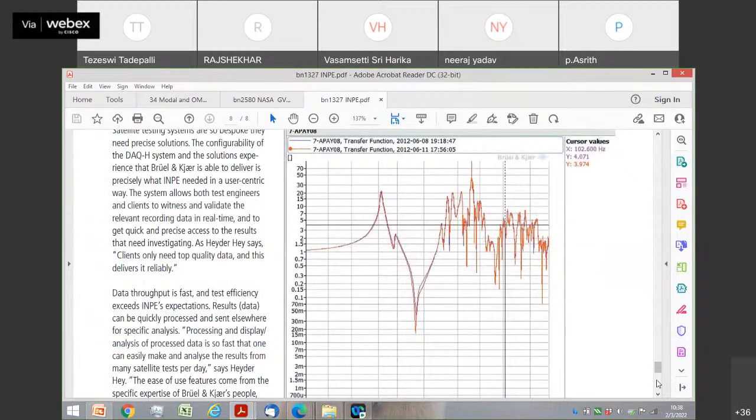Any questions, sir? Hello, sir. I'm Neeraj. Yes, yes, yes. Do you have progressive wave tube facility for the acoustic? I'm sorry? Progressive, like reverberation, we are doing acoustic testing now. So there is progressive wave tube facility. We have only the impedance wave tubes which are used for material testing, used both in the space and defense industry, NSTL, VSSC, both for studying the measuring the acoustic impedance of the materials, absorption and transmission loss.